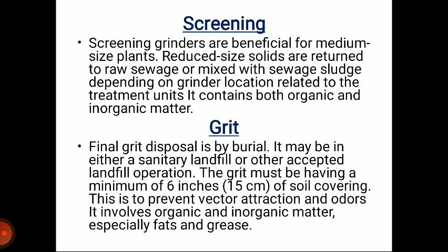Grit. Final grit disposal is by burial. It may be in either a sanitary landfill or other accepted landfill operation. The grit must have a minimum of 6 inches, approximately 15 centimeters, of soil covering. This is to prevent vector attraction and odors. It involves organic and inorganic matter, especially fats and grease.